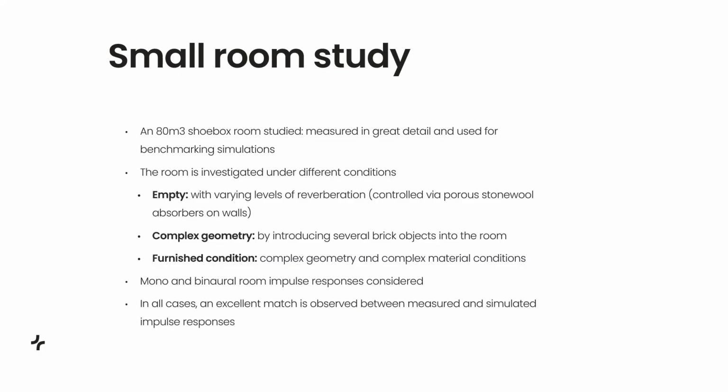It concerns a small to medium-sized room of 80 cubic meters in size. It's a room here in Reykjavik, which we have measured in great detail and then used for benchmarking simulations. And we consider the room under different conditions. First of all, being empty, but with varying levels of reverberation by having varying amounts of absorption on the walls.